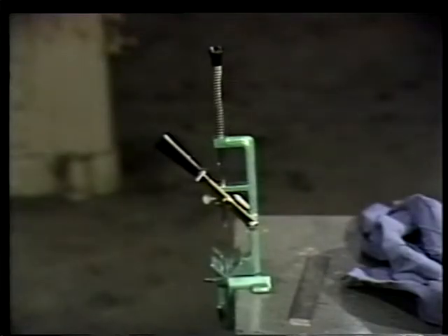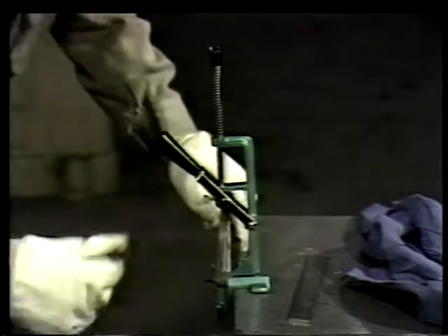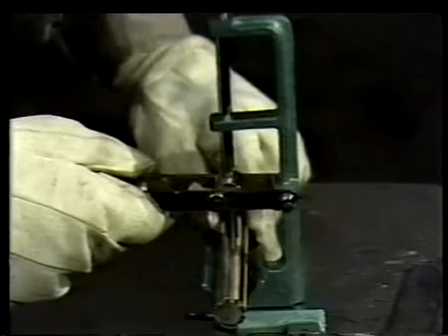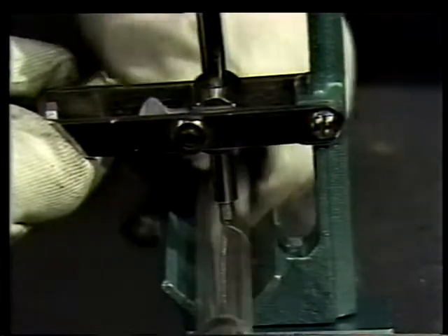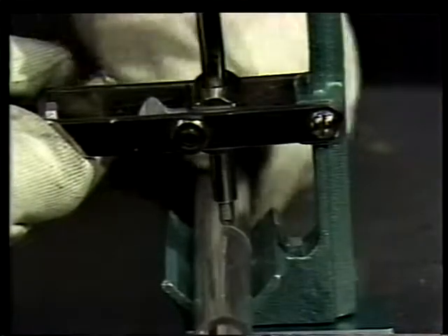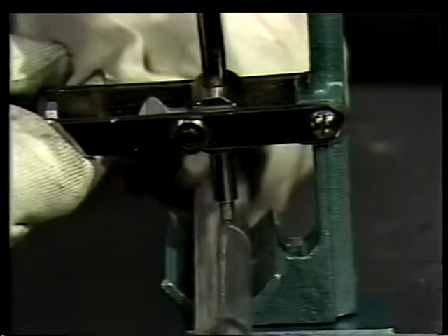The glass is cut with one of several different kinds of glass cutters. This kind is used to scribe a mark around the outside of the glass tube. Place the glass in the cutter, apply pressure to the cutting wheel, and rotate the glass. Do not rotate the tube more than once or the glass may break unevenly.